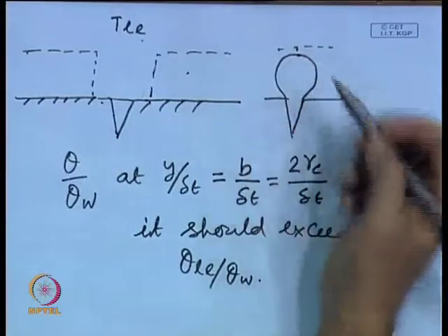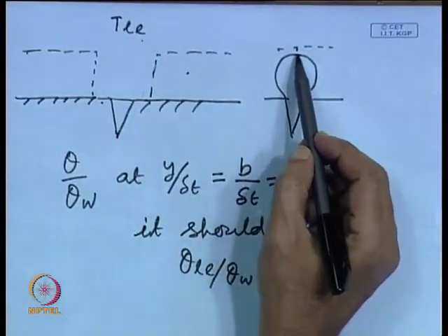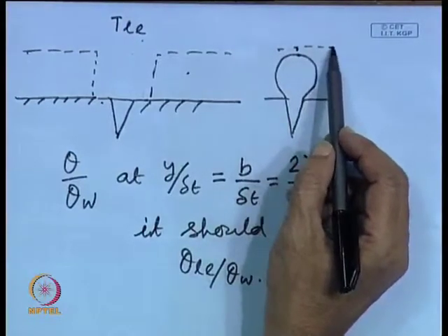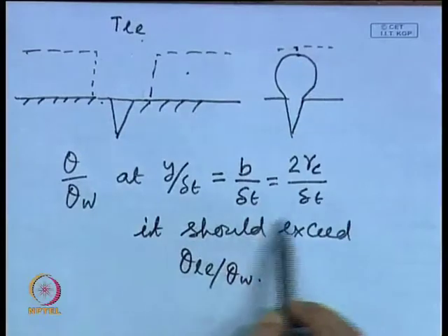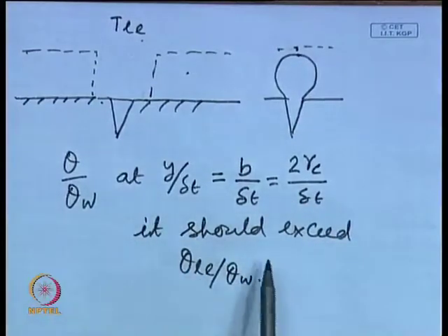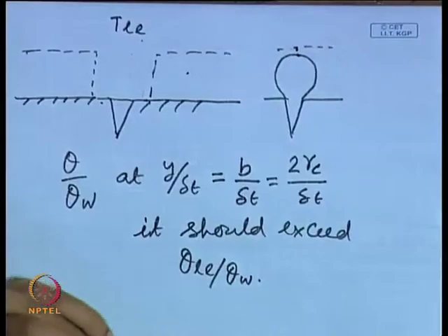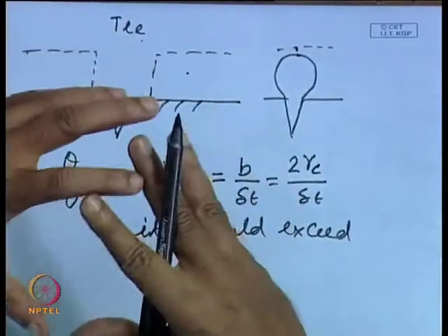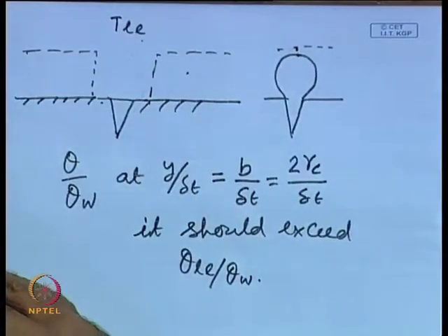At least at the limiting process, it can touch the outer edge of the thermal boundary layer, and that has been put in mathematical terms in this particular equation. Or in other words, the vapor embryo can grow only when it is wholly surrounded by superheated liquid, by a hot liquid. Why is that needed?